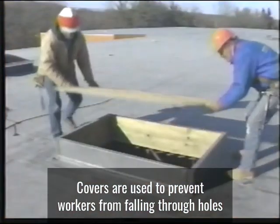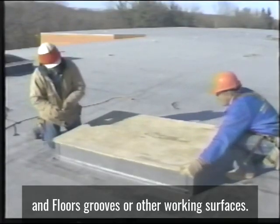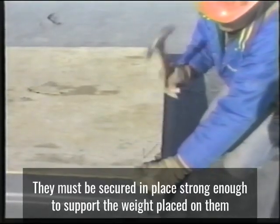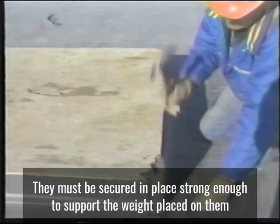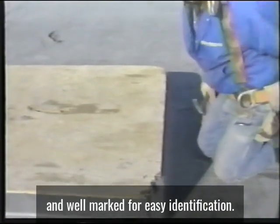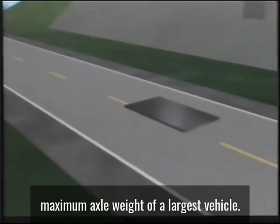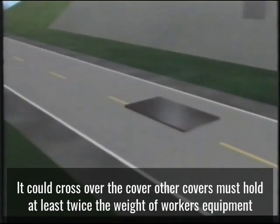Covers are used to prevent workers from falling through holes in floors, roofs, or other working surfaces. They must be secured in place, strong enough to support the weight placed on them, and well marked for easy identification. For example, roadway covers must support at least 2 times the maximum axle weight of the largest vehicle that could cross over the cover.